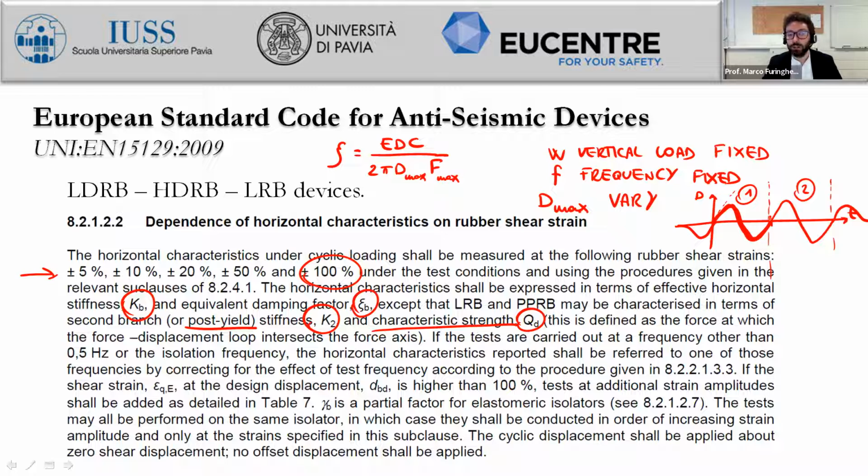My last research article tried to use very simple equations to design seismic devices, and in all the research activities that we have carried out here in Pavia, I found that this expression, even though there are strong assumptions, the fully reversed cycle, just one harmonic cycle, returns very good results when compared, for instance, with the average results of a set of nonlinear time history analyses, as well as experimental simulations with the hybrid technique.